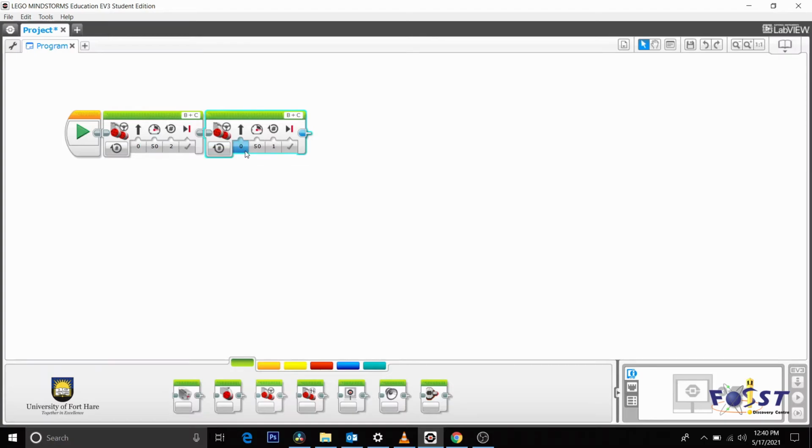As I said, the 0 here is for the direction of the robot, so we want to put it on, say, 50, just to test how the turn is. Put on 50 for 1 rotation at a speed of, let's say, 30. This controls ports B and C, and right now we want our robot to move straight and to turn right. That's all we want. So let's try that out.